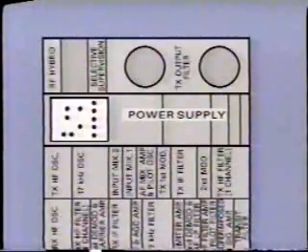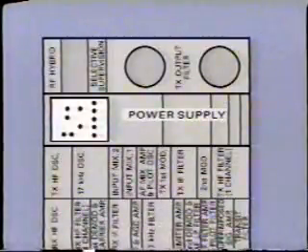Yearly inspection of these modulation levels is recommended. The potentiometers and amplifiers can drift, and the carrier could be over or under modulated as a result.